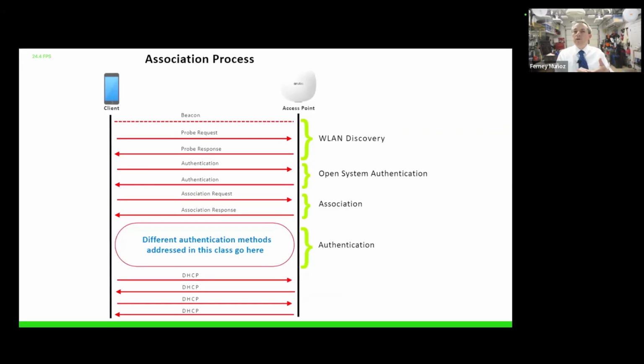I, the client, can do 21 dBm of maximum transmit power. I cannot go any higher than that. I will tell you everything about myself. Now, this is the client listing all of the capabilities of the client. So the AP is like, oh, yeah, when I talk to you, you can only do this, you can do spatial streams, you can do N, and then I know the details about you.